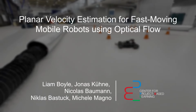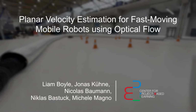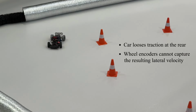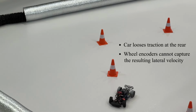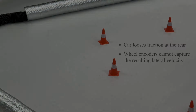We present planar velocity estimation for fast-moving mobile robots using optical flow. Accurate velocity estimation is crucial for the safe operation of mobile robots, but common approaches based on proprioceptive sensors like wheel encoders frequently fail when the underlying assumptions like perfect traction don't hold. In such instances, the use of exteroceptive sensors like cameras would allow for velocity estimation without such stringent assumptions.